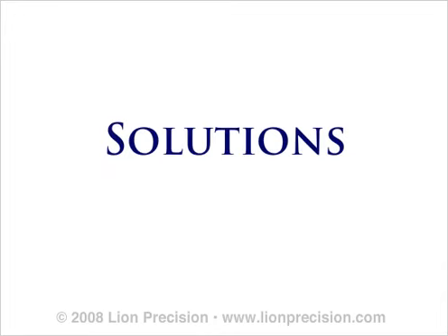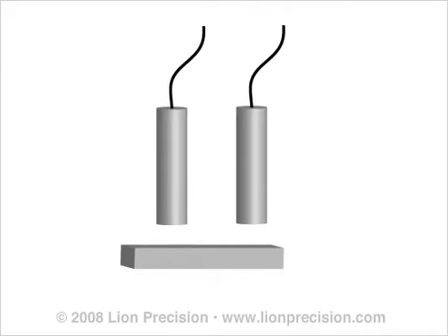When an ungrounded target is inevitable, there are techniques that eliminate or reduce the associated errors. The first and best solution uses a two-channel sensor system in which the two drive channels are synchronized but 180 degrees out of phase. In this configuration, the current path is out of one probe and into the other. Grounding is no longer an issue because the current path is provided by the second channel. The output of the second channel does not need to be used in the measurement. The second channel only provides a return path for the sensing current.